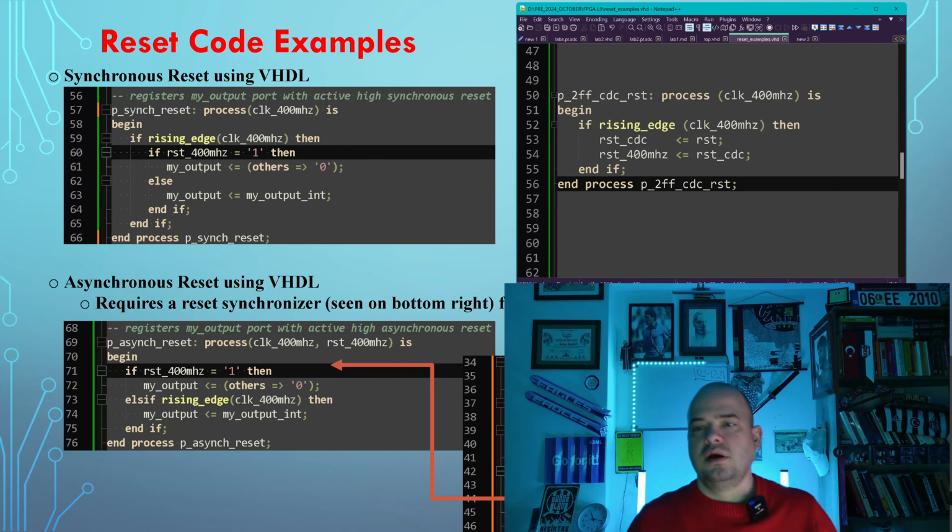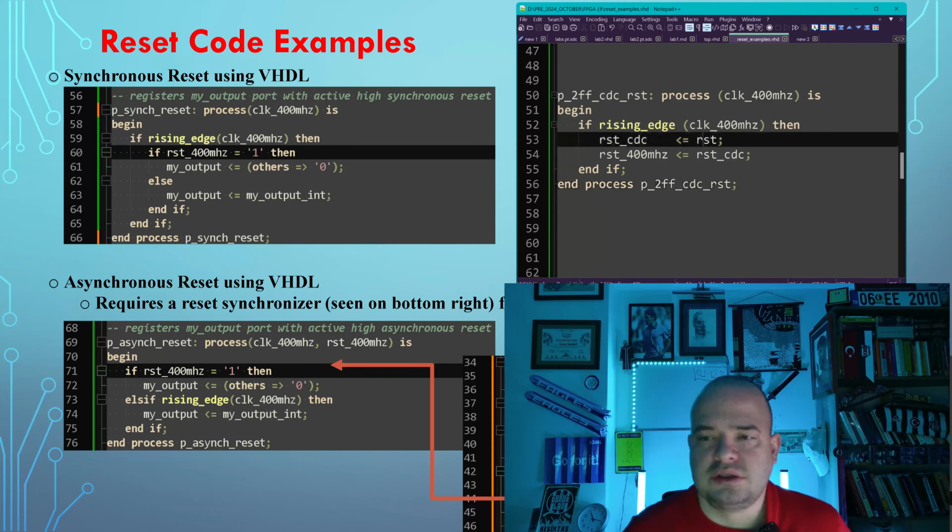So this one actually, in case I am mentioning again, two flip-flops are enough to apply clock domain crossing for the RST signal, and MTBF is still high enough, more than, let's say, 70 years, still using two flip-flops.